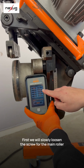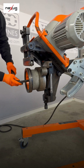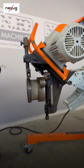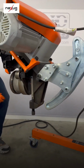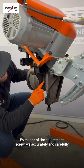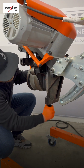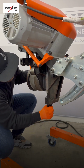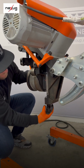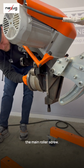First, we will slowly loosen the screw for the main roller to allow precise adjustment. By means of the adjustment screw, we accurately and carefully set the value for the initial cut, namely 15 millimeters. All set by Contramatic. We will once again carefully and precisely tighten the main roller screw.